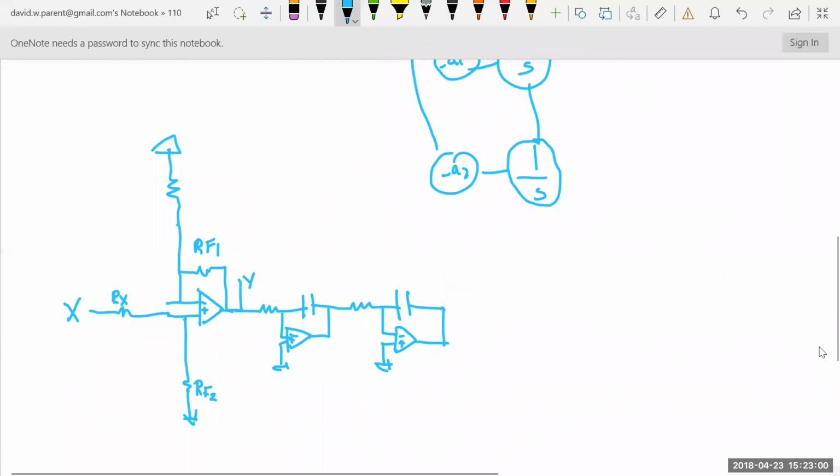All right. So one integrator, but it comes out minus. We want minus, right? So we keep it that way. And I just labeled it, you know, you can label it RA1 or just A1. When I'm doing my schematics, I do that. Now here, now we have our double integrator and it's positive, but we wanted it negative, so we have to invert it.